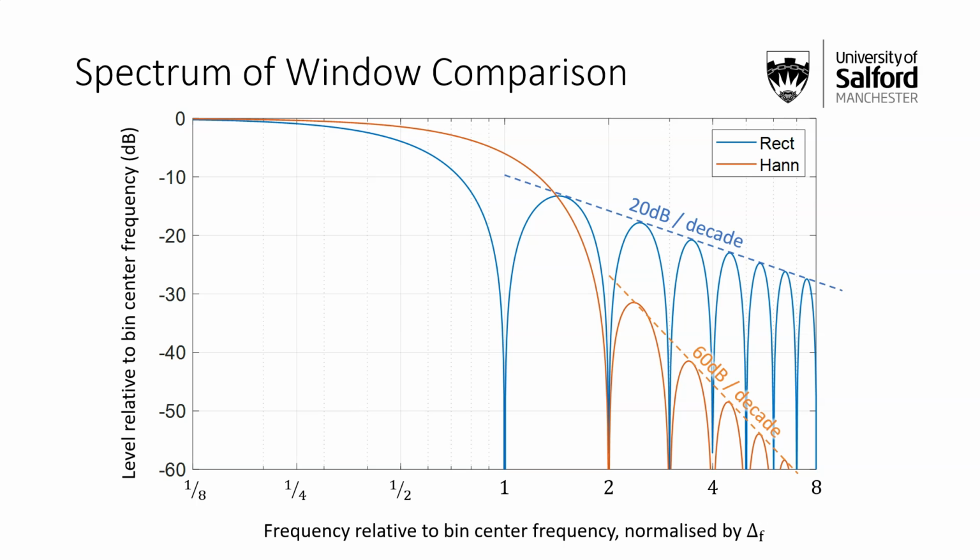So finally, just to put it all together, let's think how we might compensate for that attenuation. The Hanning window, when we multiplied by it, wasn't all 1. It turned the signal down. It attenuated the signal, and we saw that the peak value was at half the value that it was for the sinc function. So how do we compensate for that?